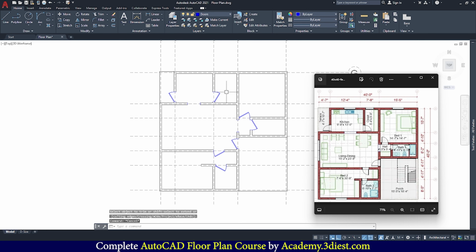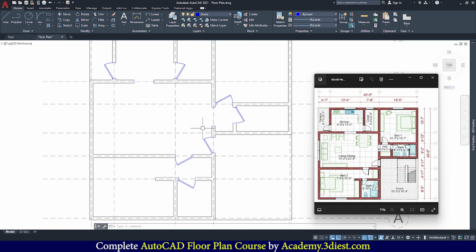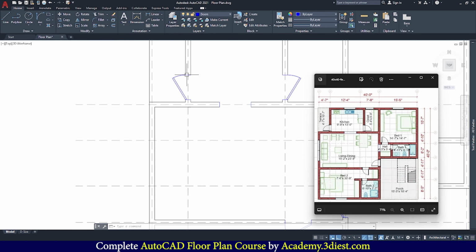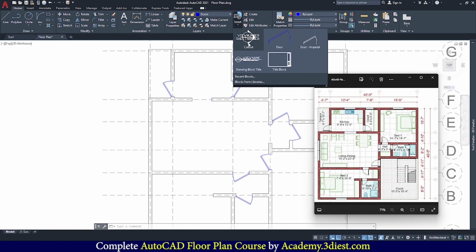So as you can see, we have just finished creating all the doors inside the door layer. Now since we are done with all the doors, here is one thing. In this current drawing, all these doors are 90° open, whereas in my floor plan, all these doors are just 60° open. We can change that by changing just one of them, because all of them are a single block copied to different places using the insert panel tool.